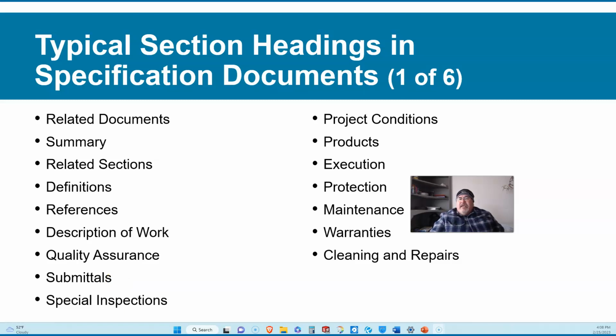What do they call it? Not a shop plan. Oh, a shop drawing, which is a more detailed drawing than you would find in the normal blueprints. It is the drawing by which the cabinet maker would build their cabinetry, and then share with the contractor what they're going to be receiving or what's going to be installed. So that's submittals. That's an example.